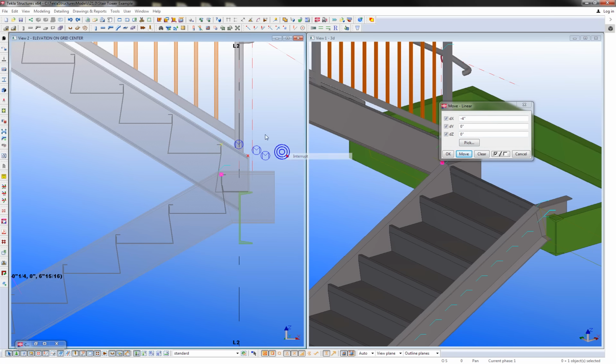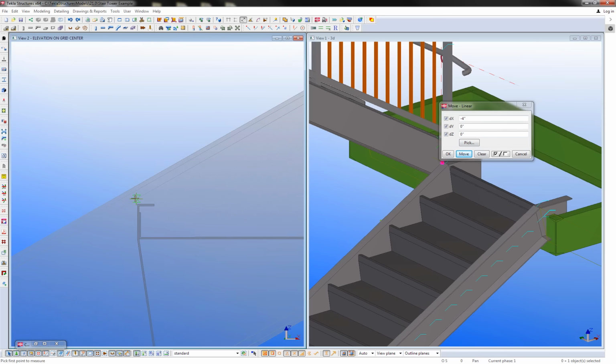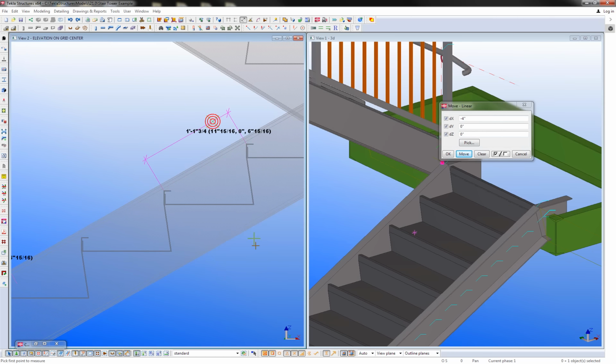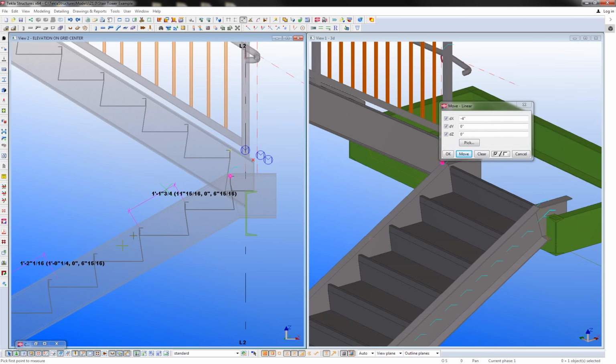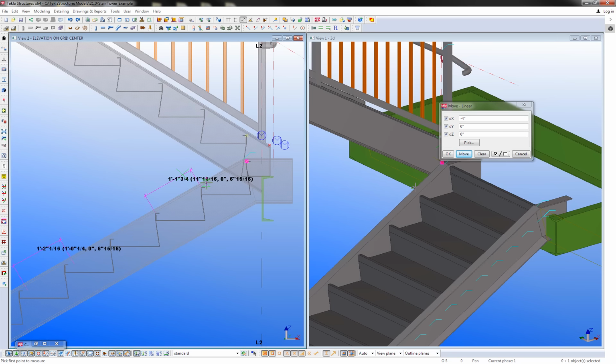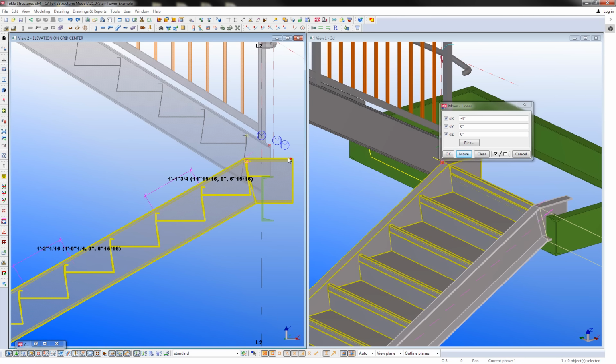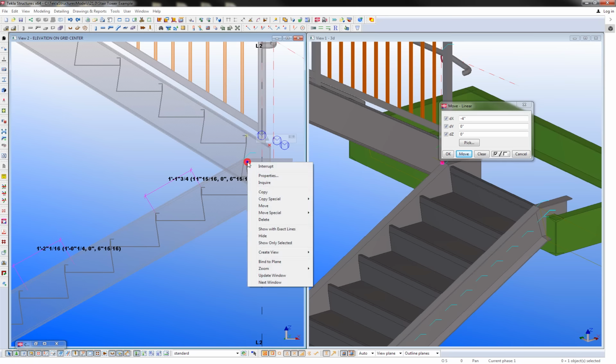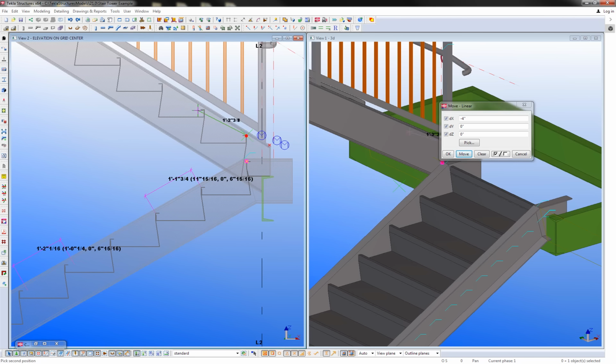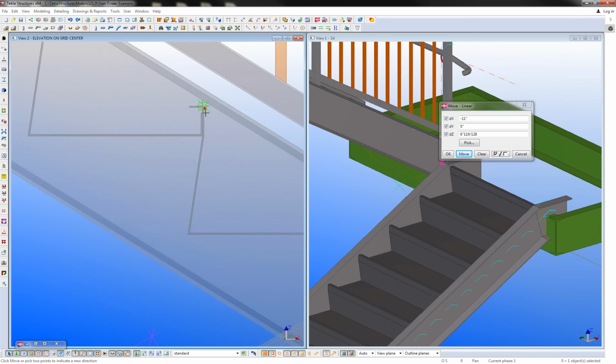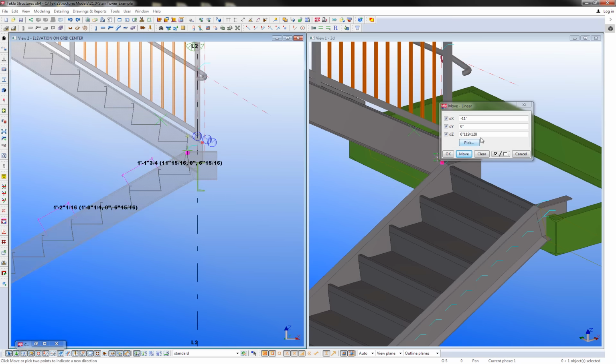So I'll move that stair back a hair, and then I'll just double check my dimensions. Again, this is just kind of the lazy man way to do this if you don't feel like breaking out your calculators. So I can see them a little bit closer. I was at 11 1/4, now I'm at 11 15/16. Let's move it back one more tread. That should do it for me, so I'll use my move special linear again. And I'll literally come back one tread width, 11 inches.